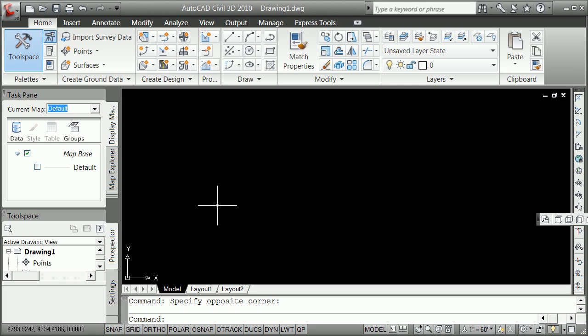Okay, welcome to Faking a Road in regular AutoCAD, even though you see Civil 3D 2010 here. I have no idea whether this will work, but I keep on talking about the fact that you can do a lot of this that you can do in Civil 3D and other programs. We'll show you a little bit in SketchUp how to use the push tool and follow along a path, that said path being your center line. You know how to use Excel to figure out points, station, and offset.